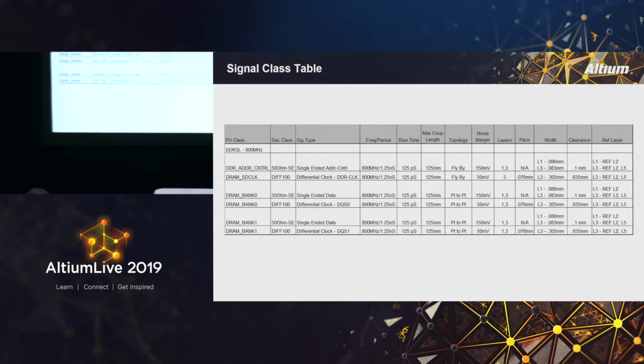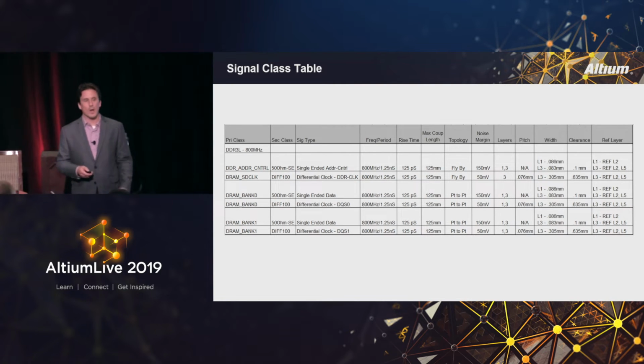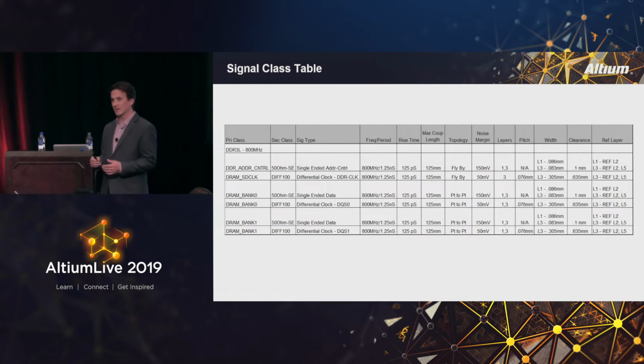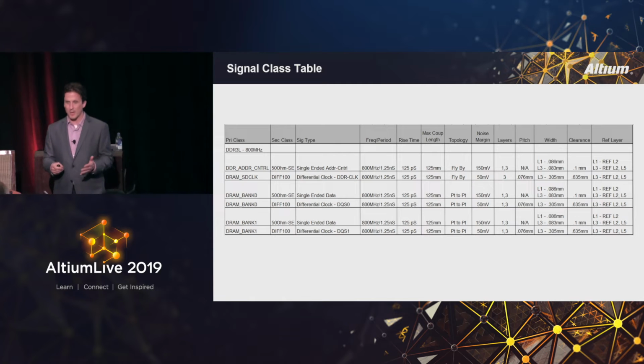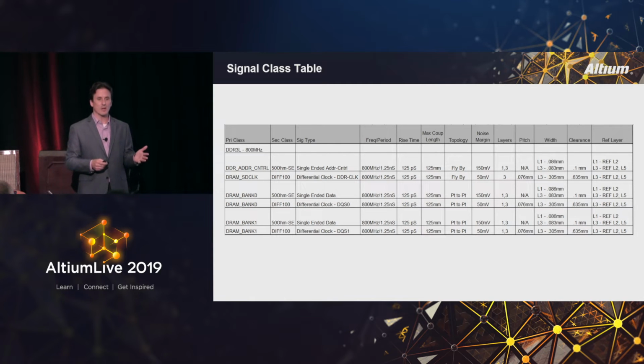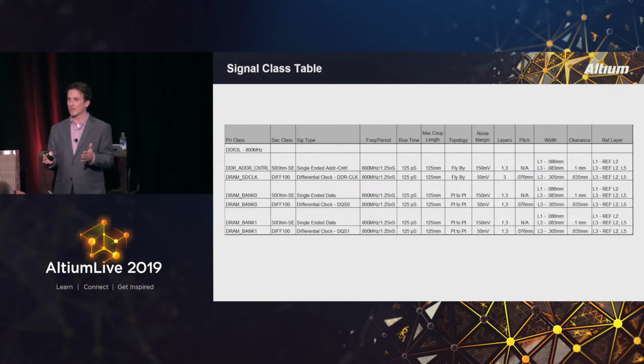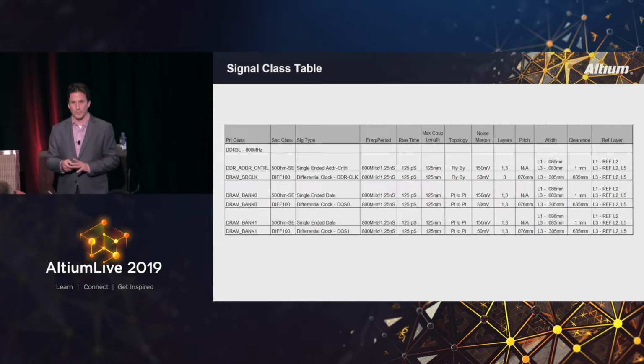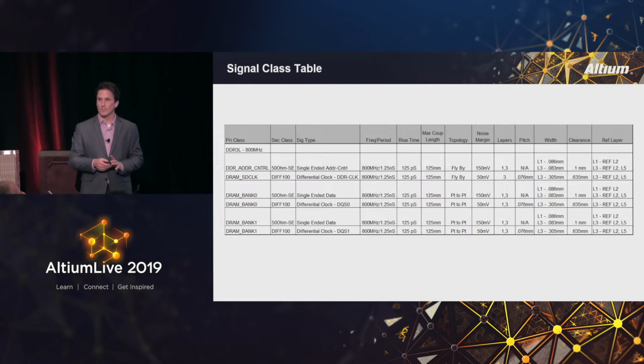Tell people why crosstalk specifically. Well, there are a lot of factors that come into signal integrity, but I am looking at crosstalk specifically because that is one of the things that I can control in my layout. It's also one of the largest noise drivers. Yes. And that's why it's important to look at crosstalk, among other things.